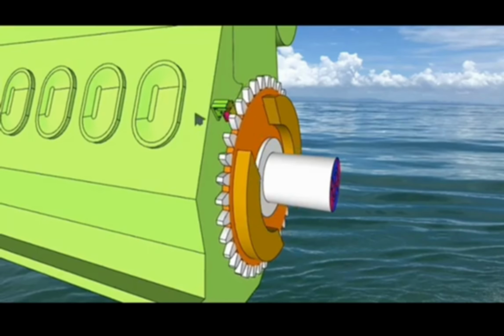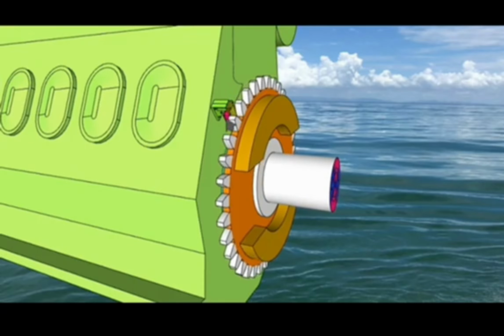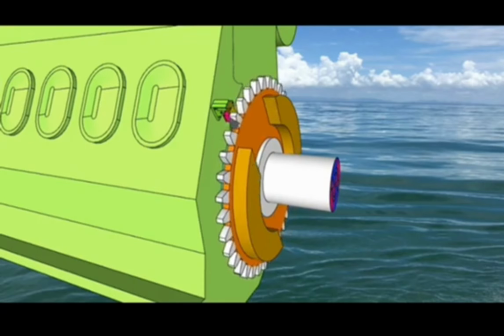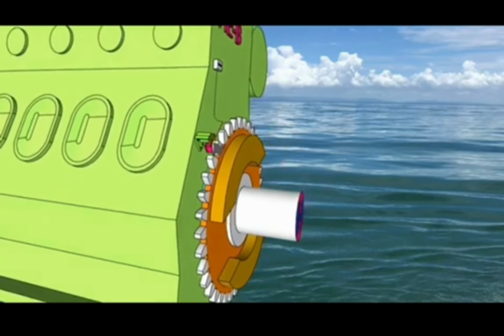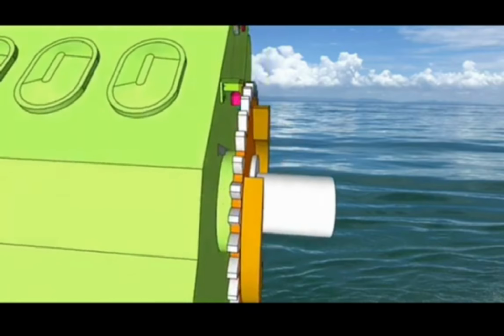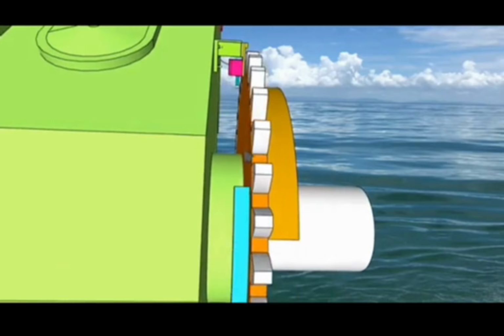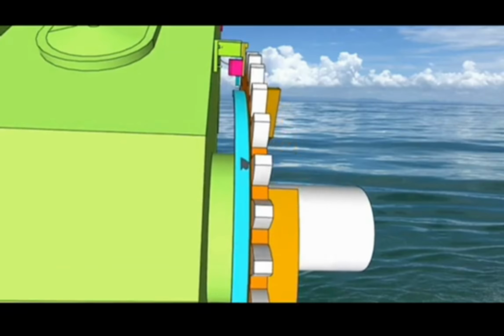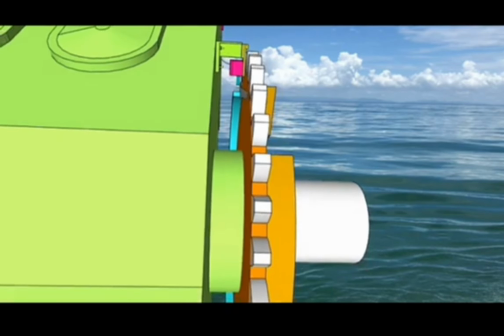This encoder is fitted behind the flywheel, and it senses the position of the flywheel by sensing a semicircular ring, which is fitted behind the flywheel. You can see that blue color ring, and this ring is fitted 90-degree offset from number 1 unit TDC. This we will discuss later.